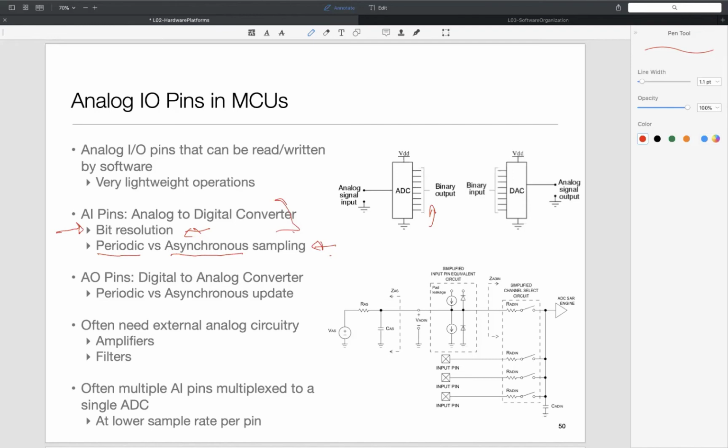Based on the frequency of the signal you want to sample. So at least twice the frequency. That's what we are taught, right? I mean, in our undergrad courses, the Nyquist rate. Those of you who are in computer science may not have heard of it, but basically one of the well-known things which comes from Nyquist and Shannon is that if I have a signal whose frequency goes up to some value f, then in order to sample and still be able to reconstruct it, rather than lose any information whatsoever, I should sample it at twice that frequency.